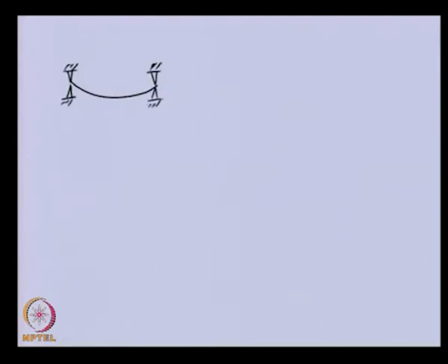So, I am trying to explain this continuous system approach by transverse vibration, and subsequently we will be analyzing torsion. So, this is a massless flexible shaft and a heavy disc we placed, and such rotors we analyzed by considering only the flexibility of the shaft and the mass of the disc.